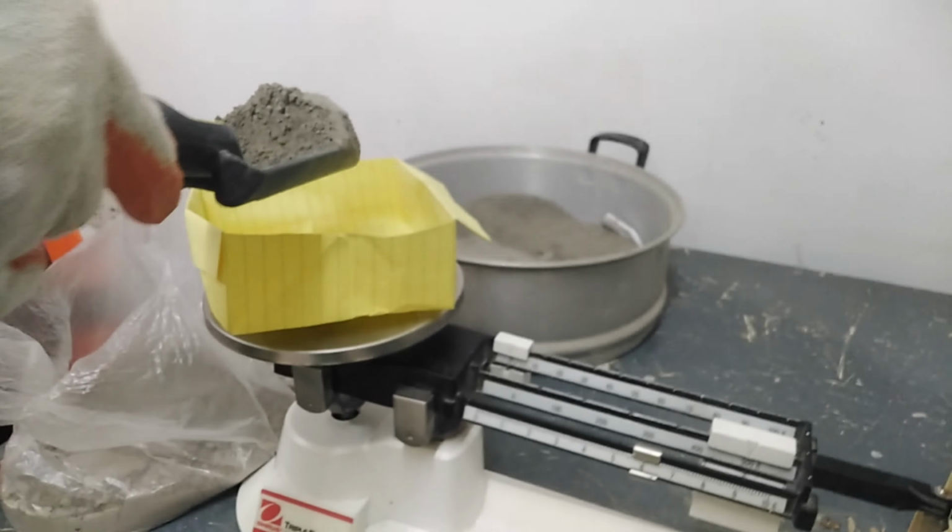Next, the gauging time will be counted from the time of adding the water to the dry cement until starting to fill the mold. Record this time as T1. Next, fill the mold resting on a non-porous plate with the cement paste. Fill the mold completely and smooth off the surface of the cement paste, making it level with the top of the mold, using a sawing motion in flattening the surface.